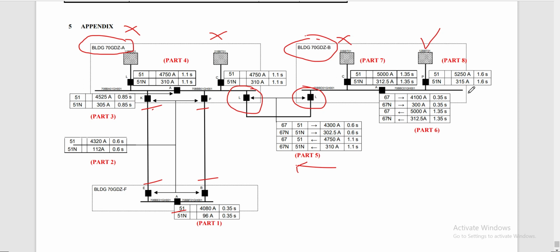Okay, the second condition. In a worst case scenario, we have power available at only building A. So, for example, it's available only on building A in this incoming feeder, and all these three and also this one are not available. Meaning here in our cross-tie feeder, if the power is only available at the building A 11 kV switchgear, the direction of the power is going this way.